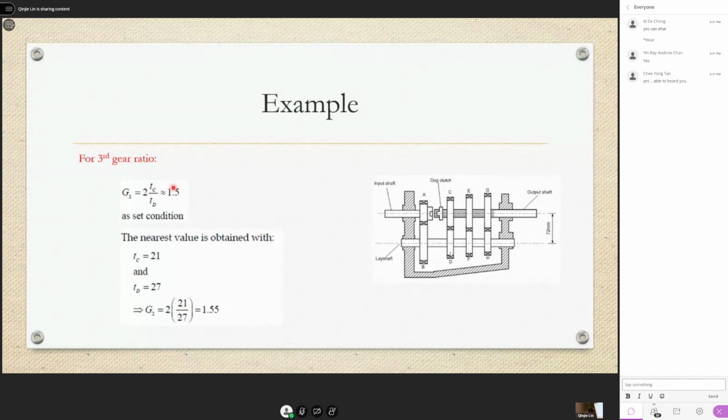So this is how engineers design a gearbox. A very typical way to design a gearbox lah. Of course, you need to know what kind of gear ratio you need first, right? You set that as what you want, then you go and design what kind of gears you need for this to work out, because you already know how much power you want to transmit for gear 1, how much power you want to transmit for gear 2.